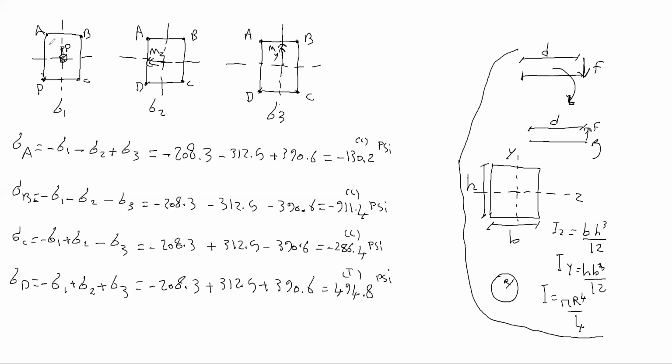Also the stress from P adds to these 2. It's very difficult to find the neutral axis just based on each one, because we need a neutral axis for the whole case. We want to see the final stress, at which point it is 0, and where it is. So now we need to find the neutral axis.